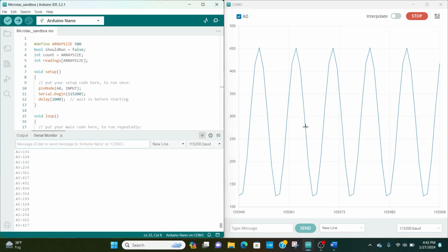Let's see now what happens when I increase the frequency of this signal. As a refresher, I've got a signal here on screen that's frozen. It's around 1 kilohertz. Now, if you recall what I said earlier in this episode, I've set that single pole filter to have a 3 dB roll-off at about 4.8 kilohertz, and I'm really right on the edge of the Nyquist criteria here. If you remember the basics, if you're sampling, in this case at 10 kilohertz, then the frequency components in your signal can't exceed 5 kilohertz, otherwise you're going to run into aliasing problems. And I can actually see that happening here, which gives me some concern, which I'll talk about in a moment after I demonstrate it.